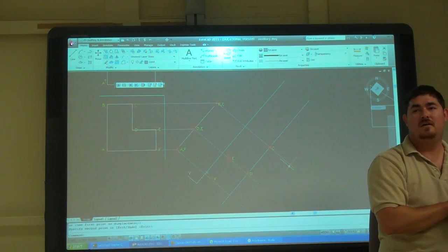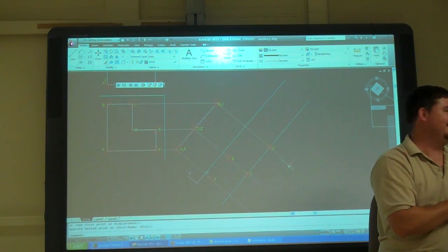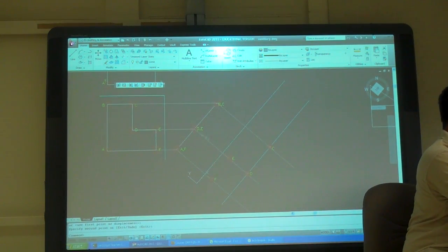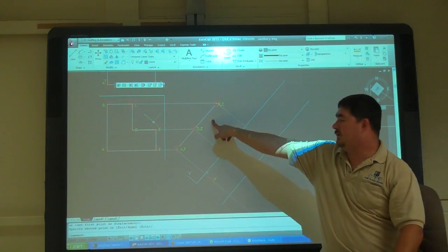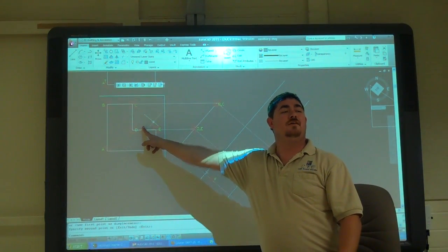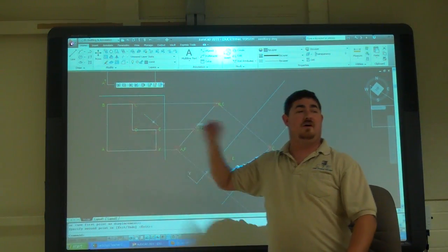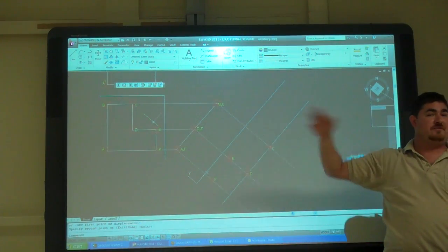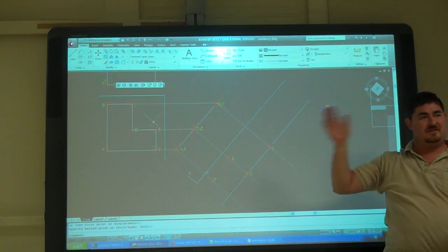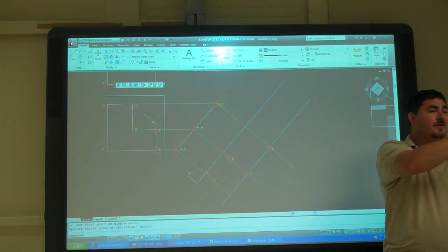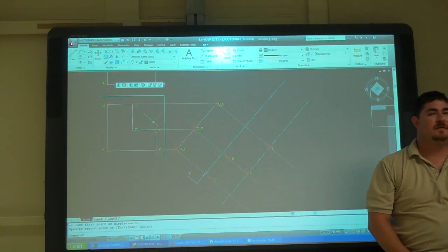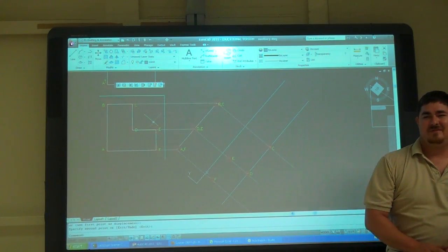Anyone lost? Well, I understood when you went from the front view, but now you're going off the side view. Same thing. Now, because I'm measuring from here, that's 2 views away, right? From here, that's 1 view, 2 views away. So that's where I do my measurement. Remember, you always measure 2 views back. If you're doing the side, you measure from the top. That's 2 views away, right? So we're still just going 2 views back, just where that second view is moves. Okay? Yes, no, kind of. Maybe when you practice.